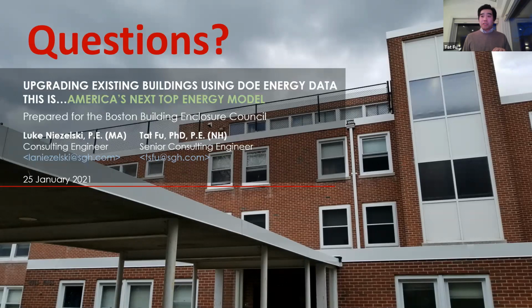I see that they mentioned we could have low E coating on the south facade while not having low E coating on the north, east and west. That is a valid, good option, especially for a building that is in a colder climate. If you're somewhere in Arizona, then you probably want low E coating all around. One thing about low E coating is it does change the color of your window. If you're going to have low E coating for the entire southern facade, that's good, but you don't want to mix and match in the same facade because it may look kind of weird.